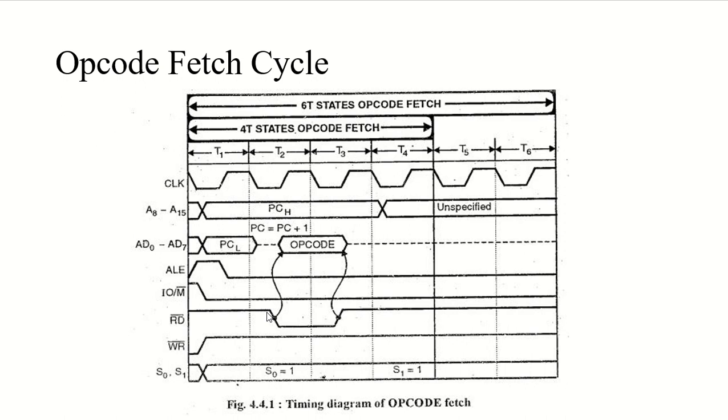So the memory device then sends the content on the data bus, AD0 to AD7. And in addition to that, the processor will increment the program counter content by 1. It will happen every single time, and I will not repeat that same thing, but it will happen in every T state. So then we have the T3 step, T3 state.